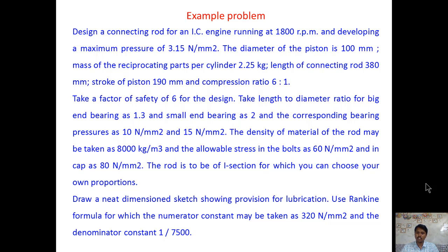Then we have to design the crank pin and piston pin. Then we have to design the bolt which secures the big end cap. Then we have to design the big end cap thickness. So, these are the four geometries we have to design.